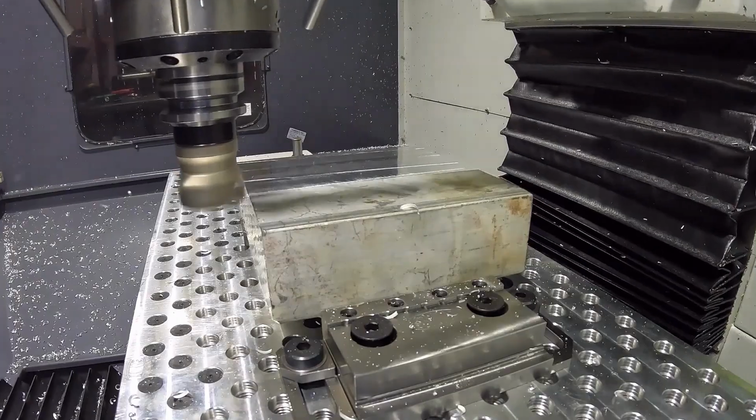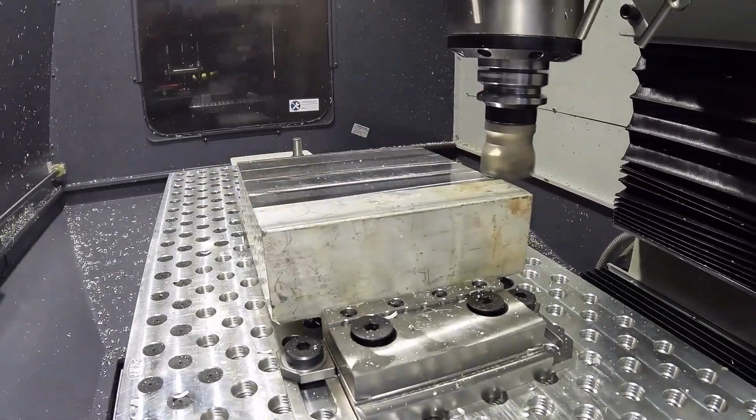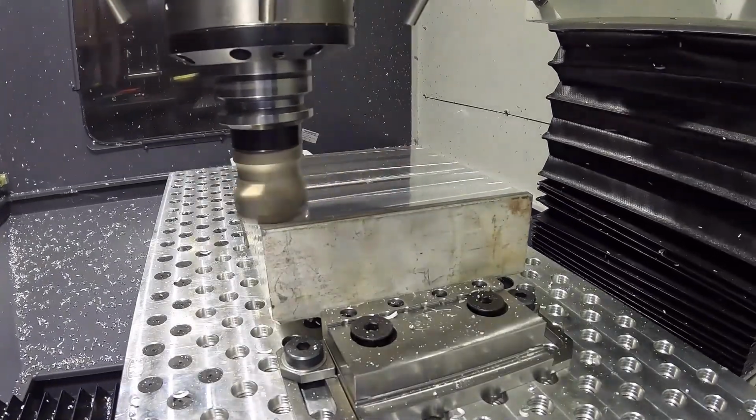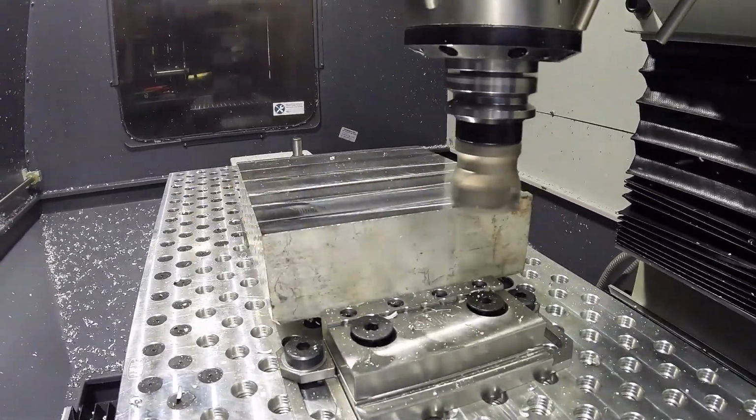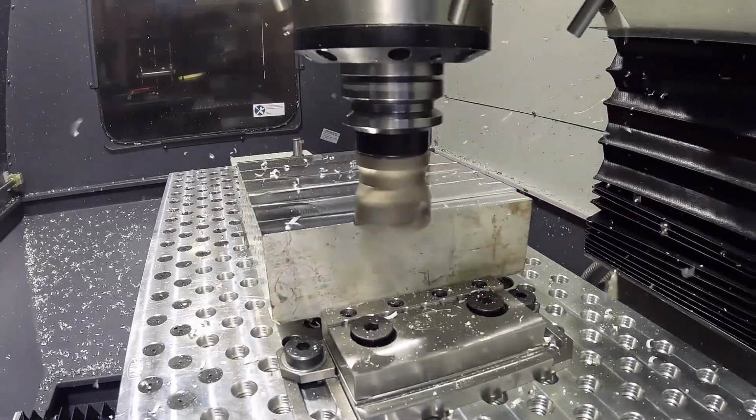This means more time freed up for you to focus on the more complex and demanding machining operations. Moreover, face milling doesn't just save you the programming time, it also optimizes the machining process. For instance, let's look at this machining example that showcases one of the options available, which is alternating the start points of the toolpath between each level. This smart feature helps reduce your non-cutting time, making your machining process even more efficient.